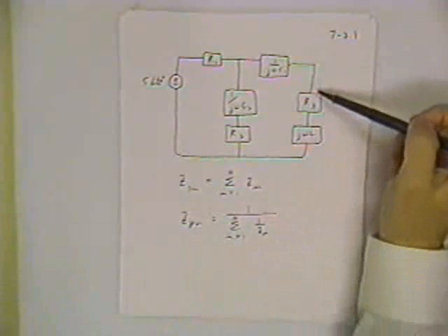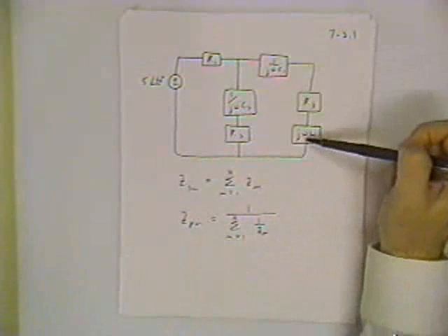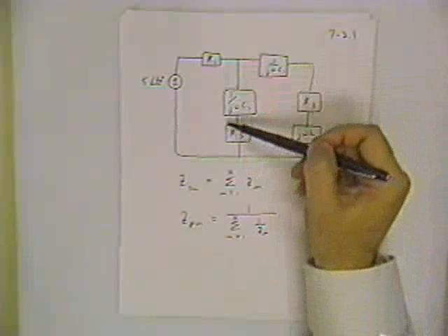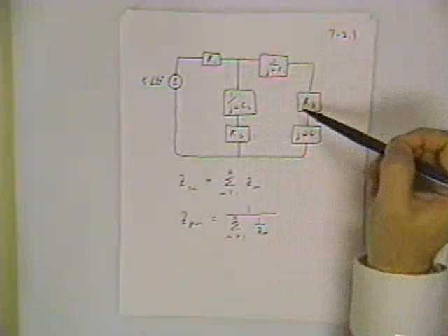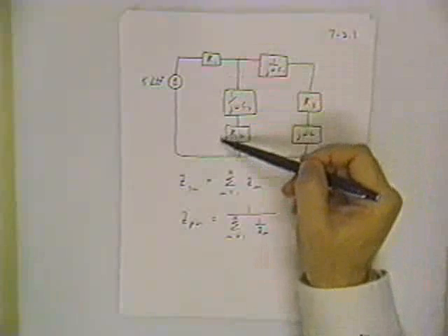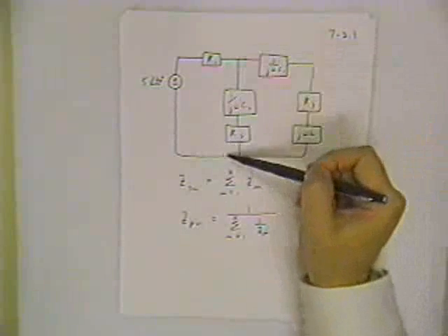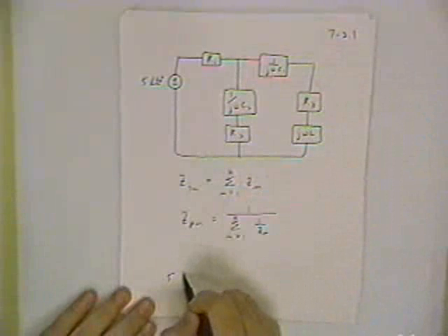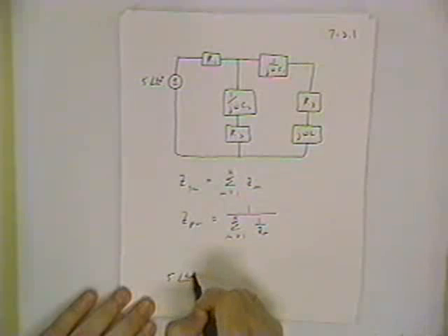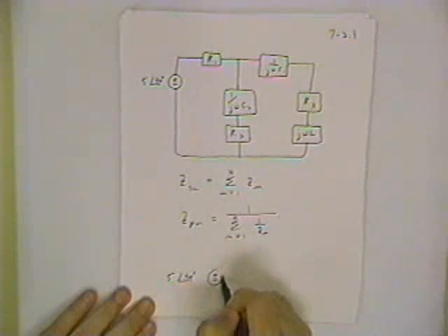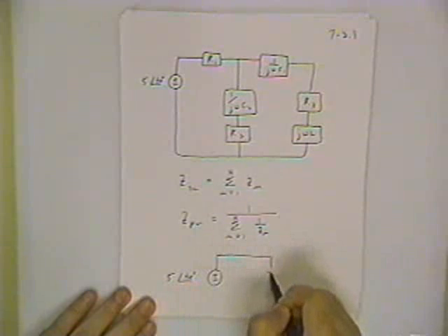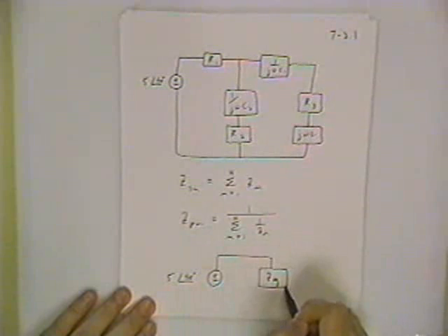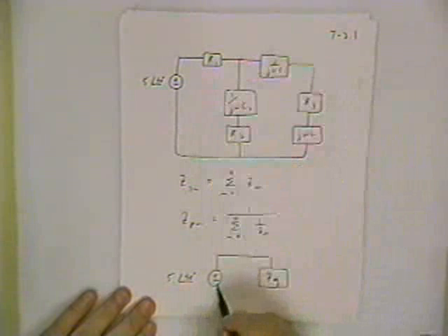So with numerical values substituted all along here, what you would do is take one grand total impedance for this branch, the grand total impedance for this branch, combine those two in parallel to come up with a single impedance for this whole network, and then add R1 to that. Then what you would have is a straightforward exercise in Ohm's law. It says I've got a ZEQ now. That's the impedance equivalent of this entire network of resistors, capacitors, and inductors.